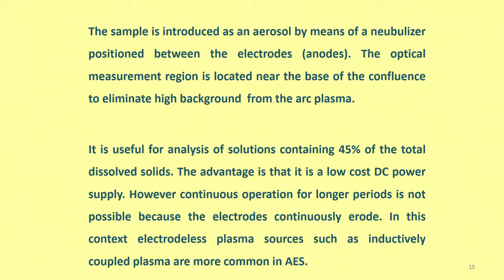During the arc, the material will burn. So, the gap will increase, and the arc will become less intense. So, DC arc is not really suitable because you do not know when the arc will go off. Only when they are very near, voltage is very high, arc is struck. So, as the material burns, signal will fall down. The arc may go off, then you do not have an excitation source at all.